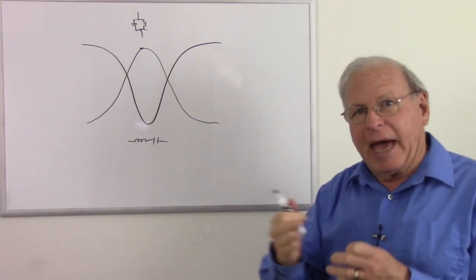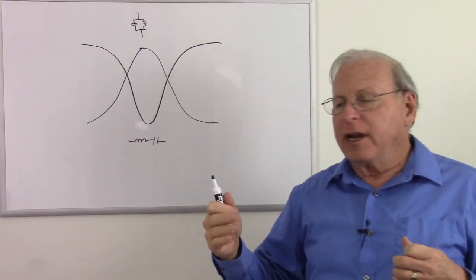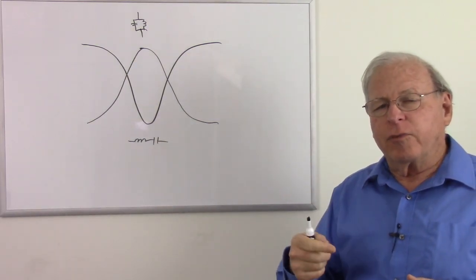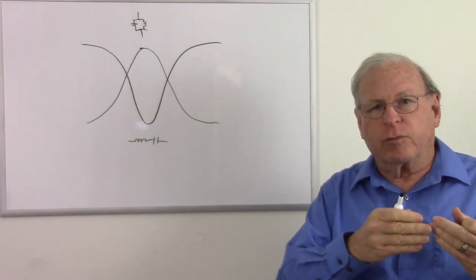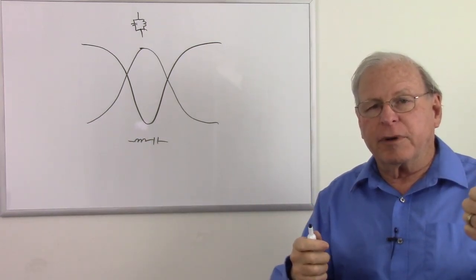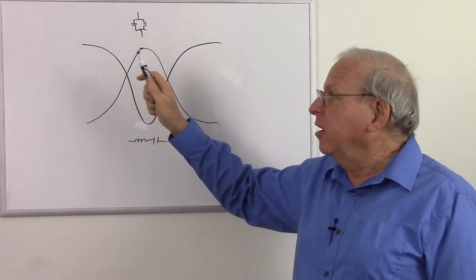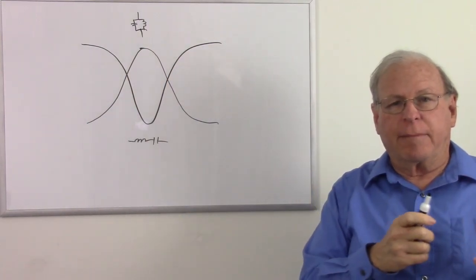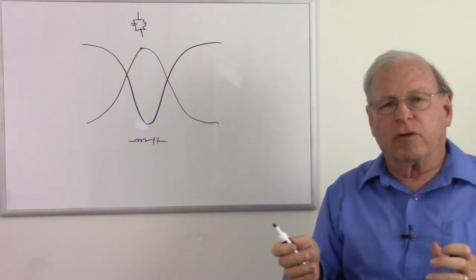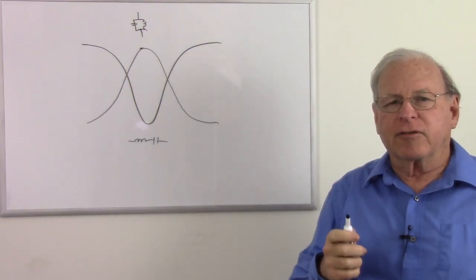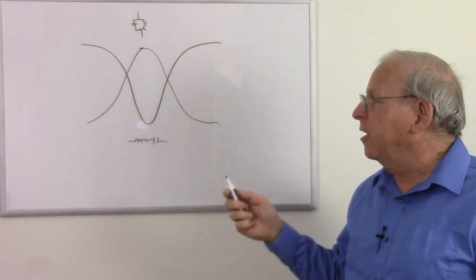Well, we could pass information from one circuit to another, but using an inductor and capacitor in series, we could let certain frequencies pass from one circuit to another, but not those above and below. Or using the capacitor and inductor in parallel, we could have a circuit that passes frequencies from one circuit to another, but allows frequencies near the resonant frequency through, but does not allow frequencies above and below the resonant frequency.